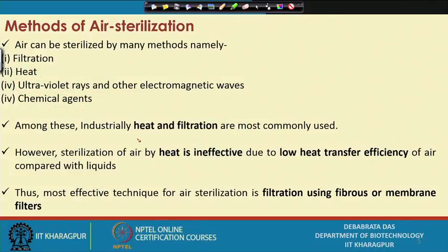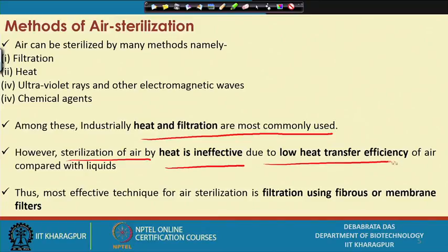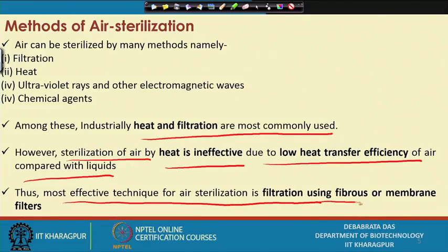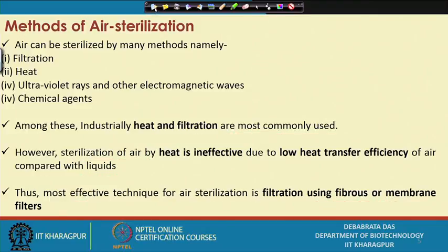Among these, industrially, heat and filtration are the most commonly used. Heat is ineffective in the case of air sterilization, due to the low heat transfer efficiency of air as compared to liquid. Thus, the more effective technique of air sterilization is filtration with fibrous and membrane filters, as I just discussed.